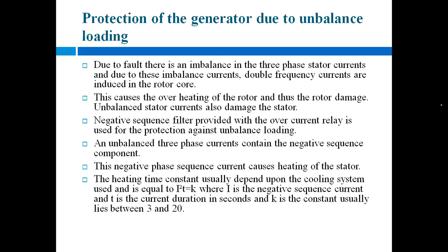The angle between the currents is actually 120 degrees, but it becomes less or more, which means the system is not balanced. We say the system is balanced when the angle is exactly 120 degrees and the current flowing through the neutral wire is equal to 0.